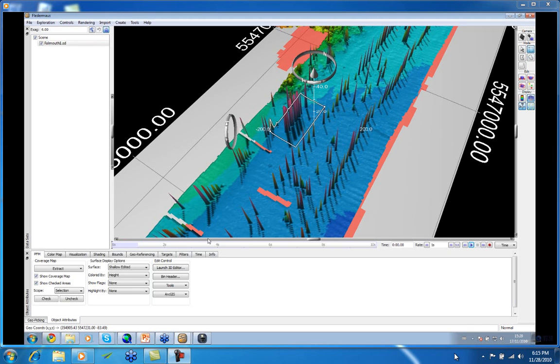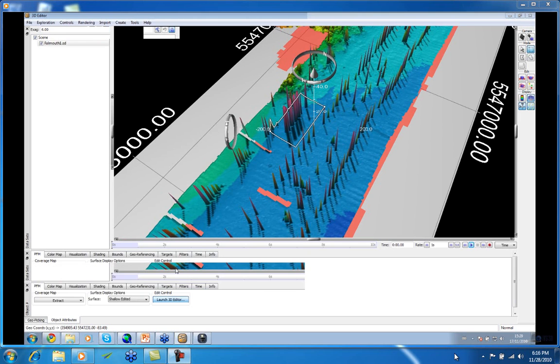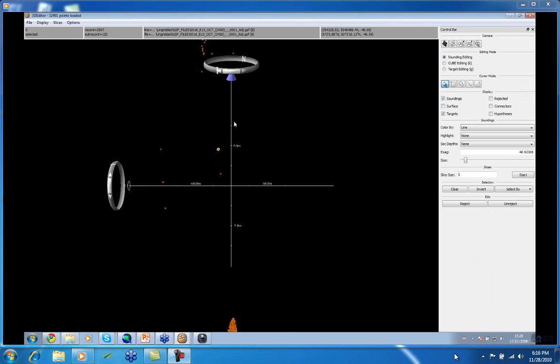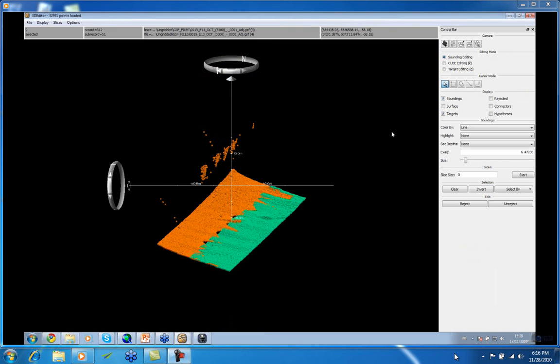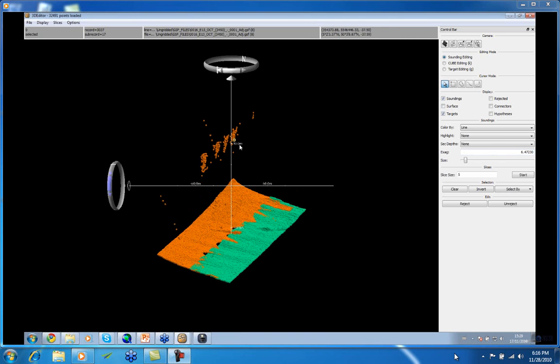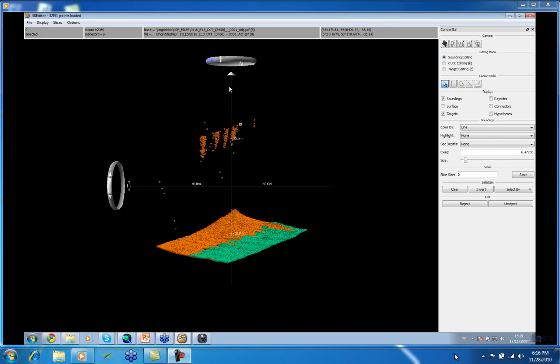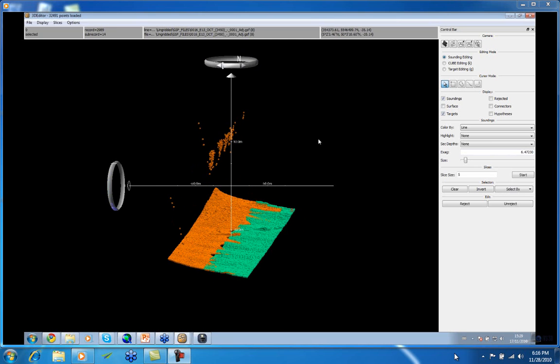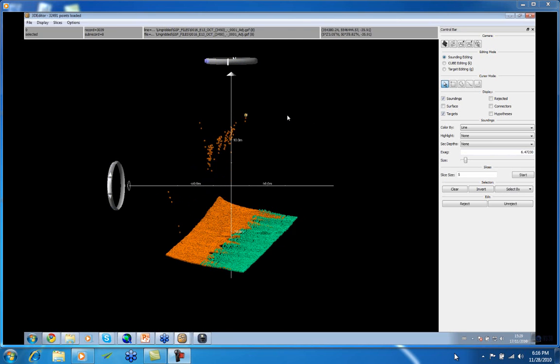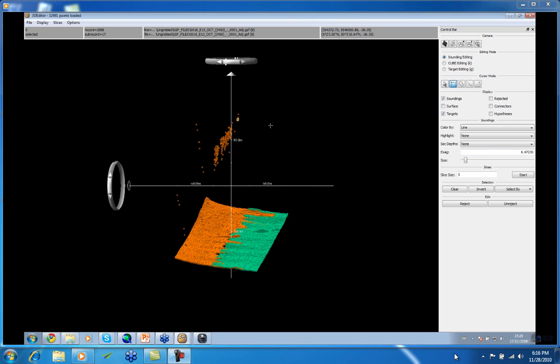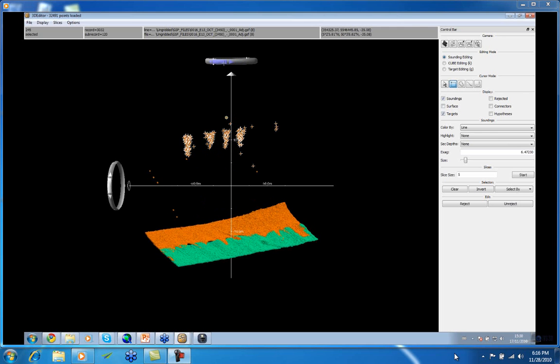And this will just bring the exaggeration down a moment. You can also bring the exaggeration down using the, sorry, I've just got my other bits and pieces on the screen here. You've got the exaggeration window over here. So in select mode, you can use the widgets or not use the widgets, or either in explore mode. If you go to select mode, then you're now doing something different. You're now selecting points. So if you want to move around, then you have to use the widgets. So you can select the points you want to delete, and if you make a mistake, you can clear them.